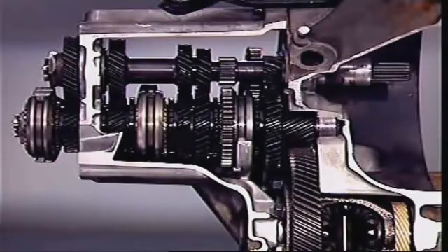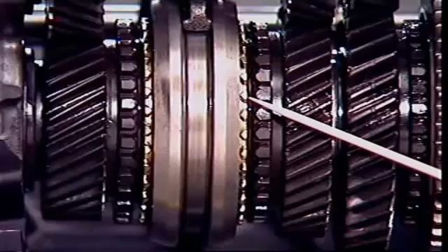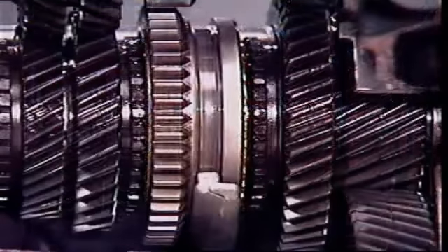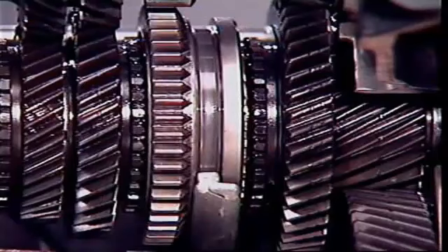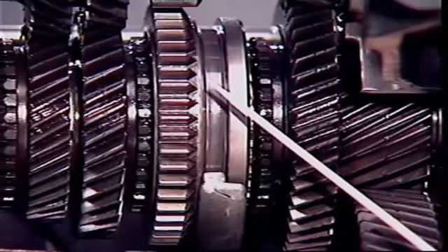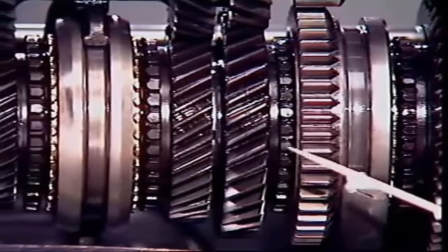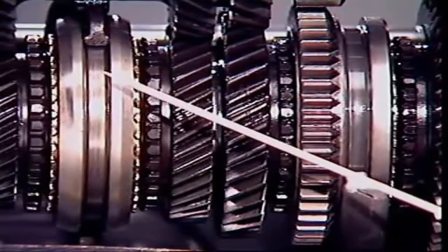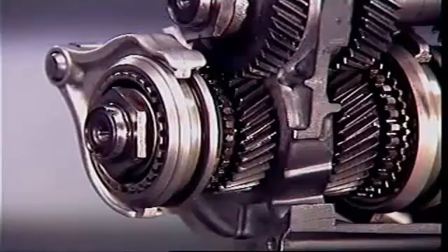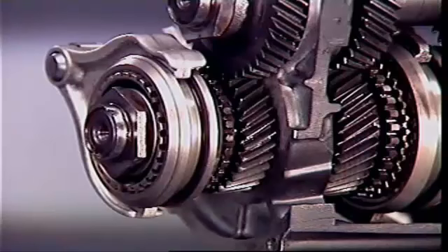In transaxles, the synchromesh unit plays a similar role. It is located between the end of each engagement sleeve and the gear. In this layout, the engagement hub and sleeve for first and second gears is on the secondary shaft, as is the third and fourth speed hub. The 5th gear engagement hub is at the end of the secondary shaft, furthest from the main drive pinion.